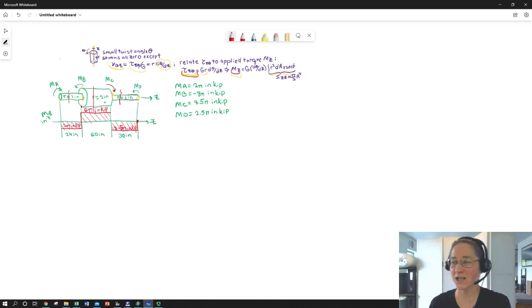Obviously, with a big, thick shaft, where we're very likely to be in plane strain, those of you who are going on to material science, this is the area that you would be probably thinking about applying your K1C, your fracture criteria, because you will definitely be in plane strain in the middle of something that big and thick. But it's for later. Just an aside, our plane stress, plane strain recognition, but for now we're just going to eventually be comparing yield criteria, so think more circles and yield. Okay, but first things first.